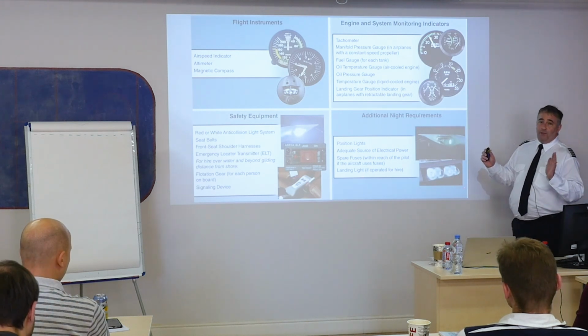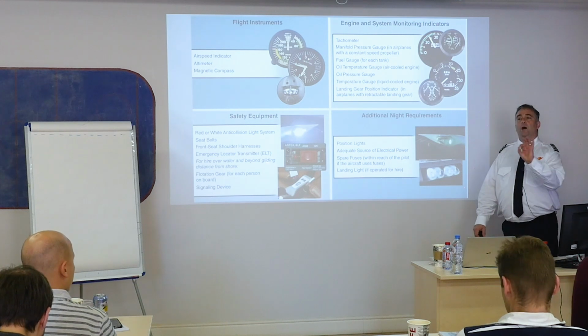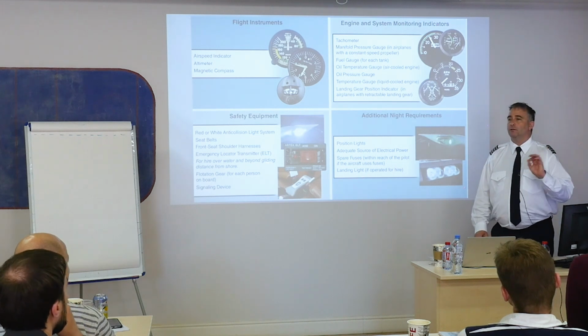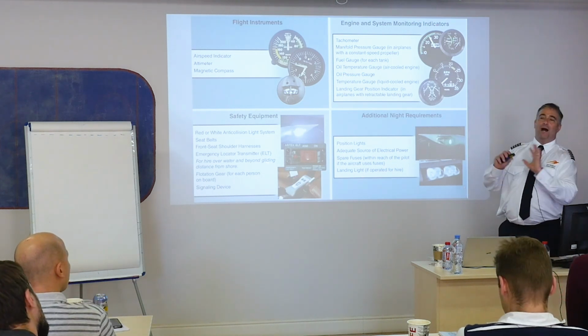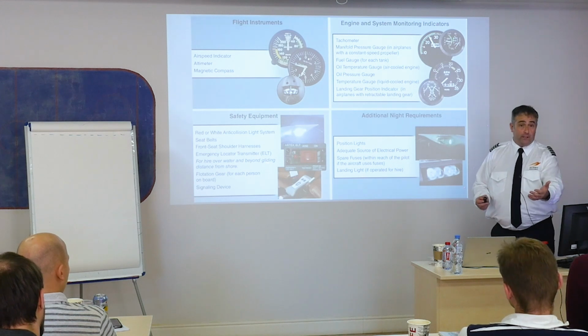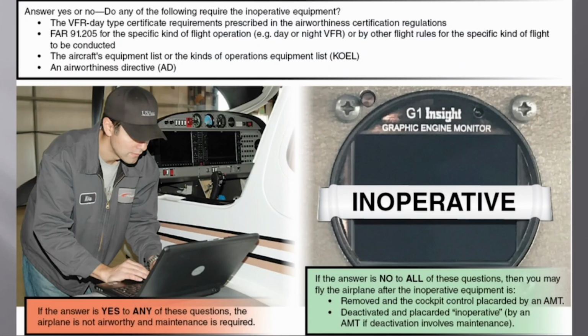Now, some of the stuff in the airplane might not work. As long as it's not any of this, that's okay. Nothing wrong. I'm saying some of the stuff might not work. I might have an ADF, navigation radio, that is not used very often by anybody in the United States, the Caribbean, South America, wherever. Okay? It's in the airplane. It doesn't work. I'm not going to cancel the flight because of that. But I still need to report it to maintenance. And it's supposed to have this label on it if it's not operating properly. It has to be placarded that it's not operating properly.